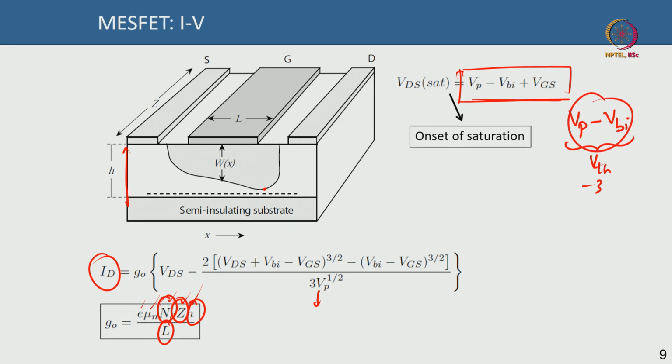Now at threshold voltage you pinch the channel off completely, however you have a drain voltage here, a Vd. The drain voltage modifies the depletion, and you have a wider depletion towards the drain and narrower depletion towards the source. To have the wider depletion towards the drain, your gate bias also comes into the picture. How much gate bias you are applying to get the drain pinch off?